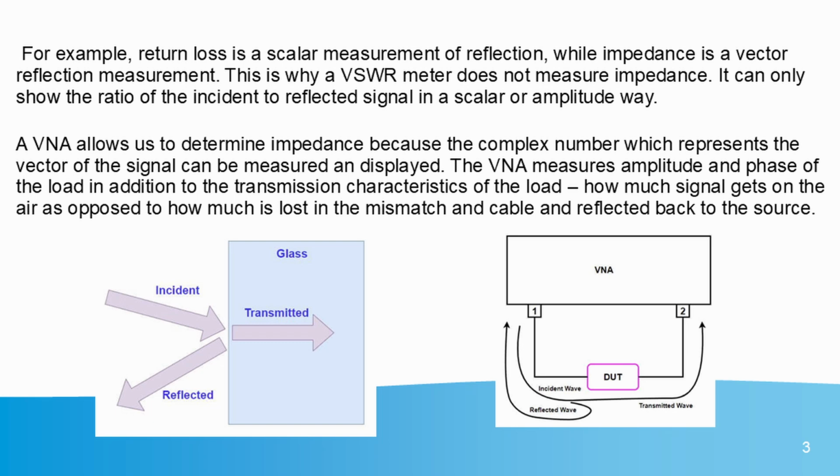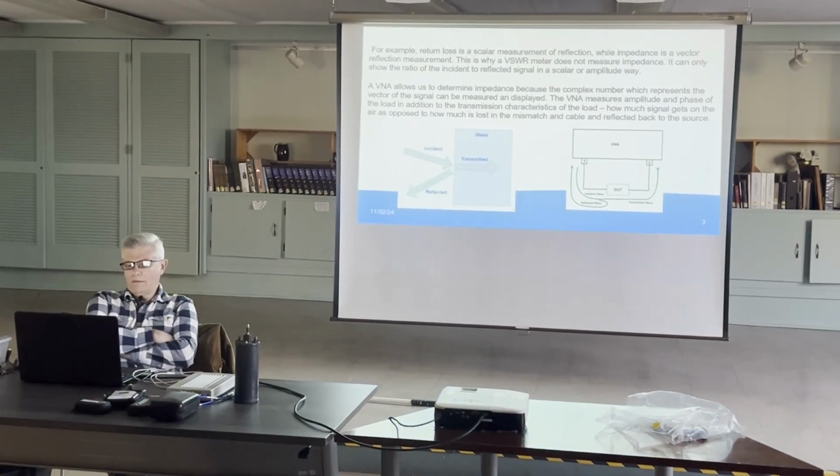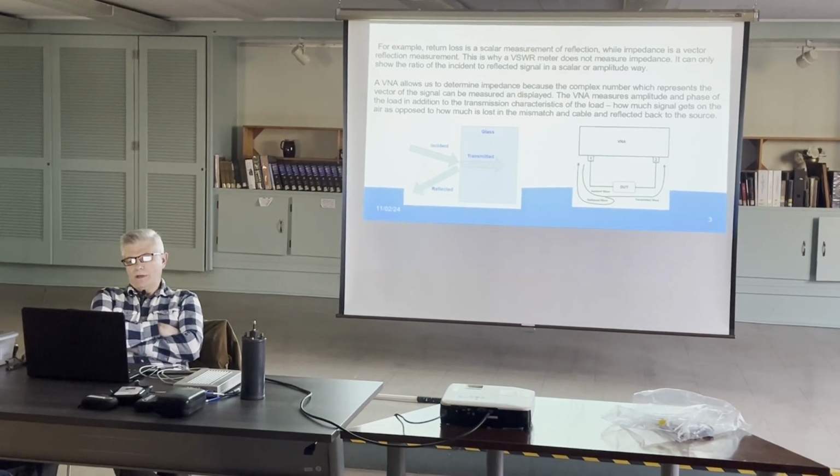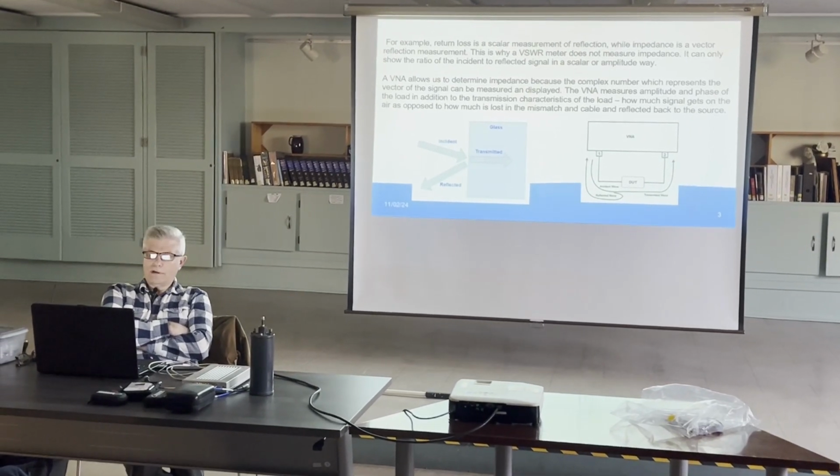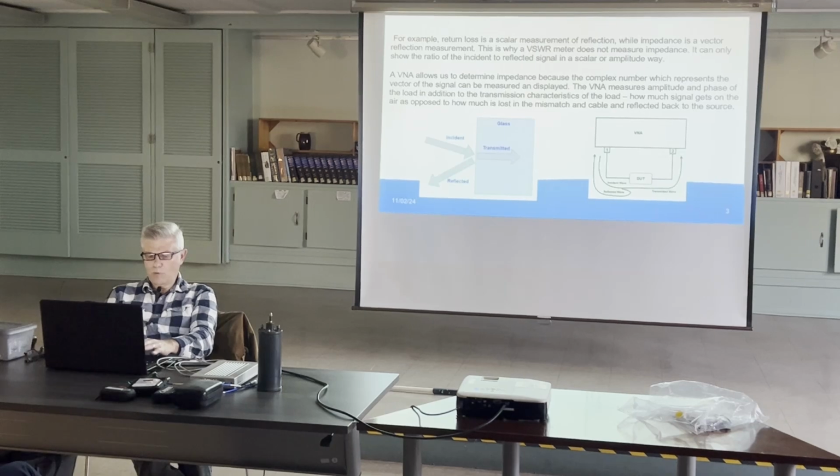In this particular situation, you have a number of S parameters. This would be what we would call an S21 measurement, where we are listening on port 2 and transmitting on port 1. But you can also have an S11 measurement, which is simply sending the signal on port 1 and then receiving it back on port 1.